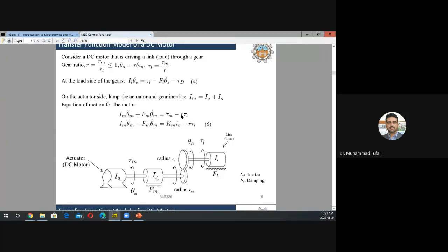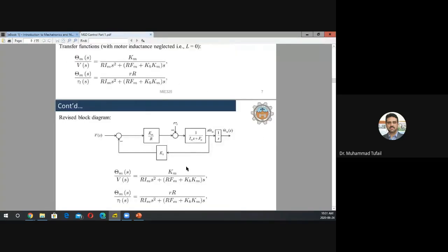So if your R is way less than 1, anything that happened to the right of the gears does not reflect to the left side of the system. We have decoupled the system. And that's the role that the gears play in the system.